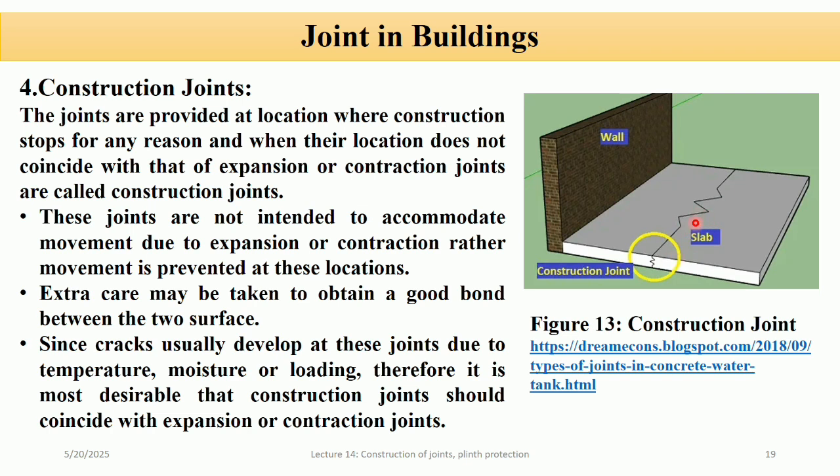The two parts are expected to act as a single unit, and a strong bond is essential between the old and new concrete to ensure structural integrity. Special care is taken so the old surface is clean, roughened, and sometimes treated with bonding agents before new concrete is poured.